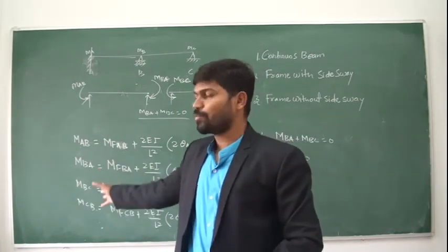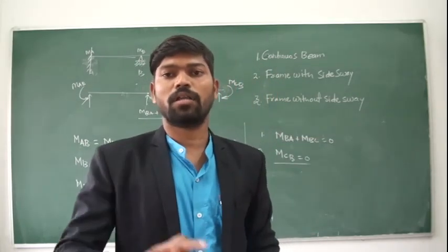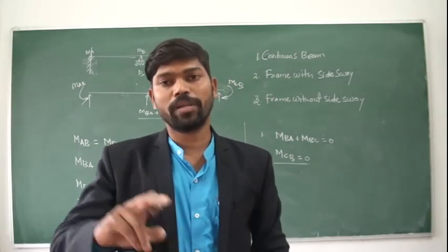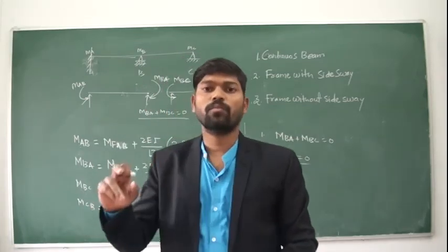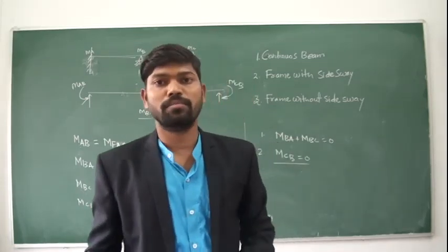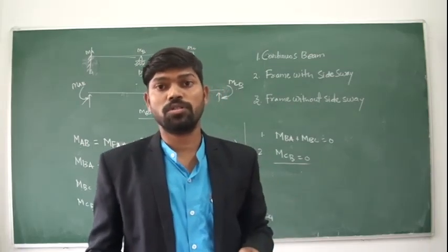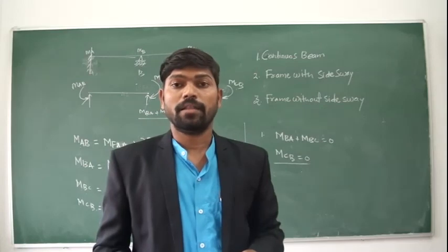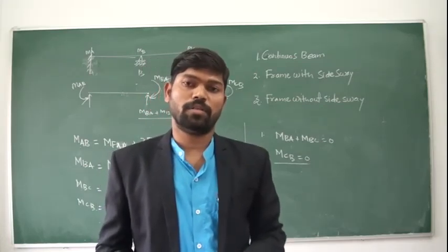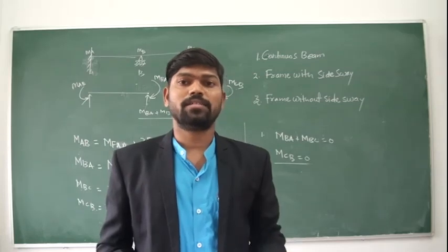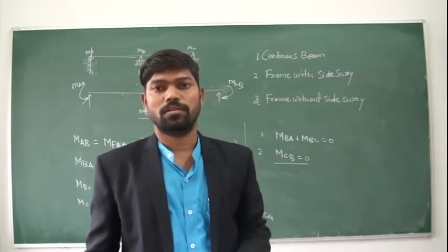Once you calculate the support moments, you can draw the free bending moment diagram and superimpose the support moments on this free bending moment diagram to draw the resultant bending moment diagram for the given beam. Okay, so this is the procedure for the analysis of an indeterminate beam by using the slope deflection method. In our next lecture, we will solve one numerical, one beam by using this method. Thank you.